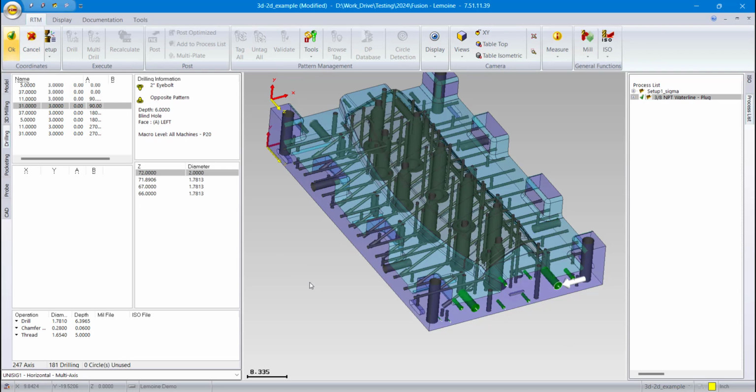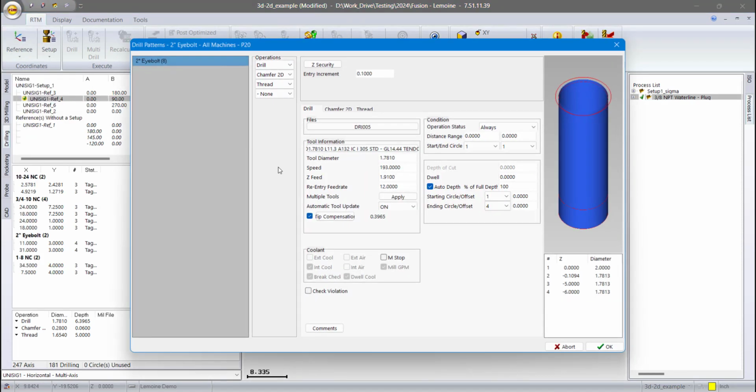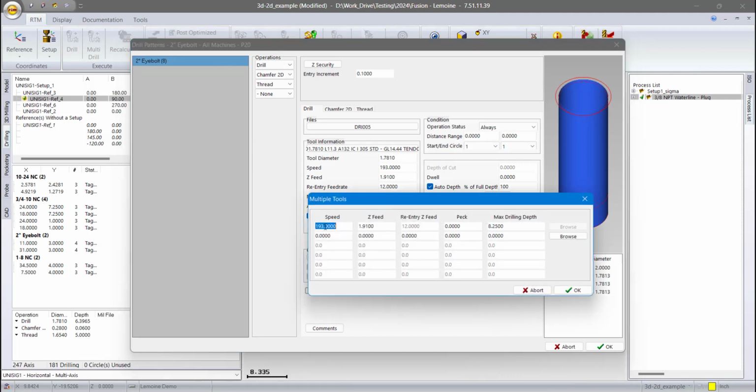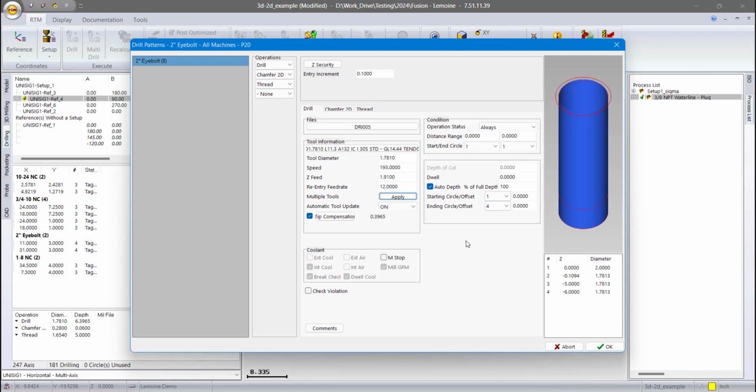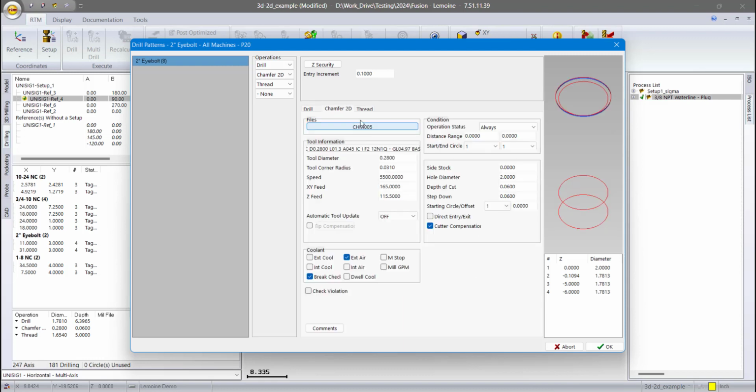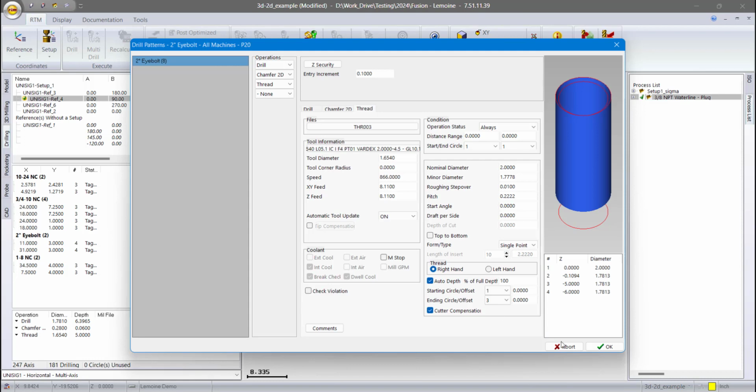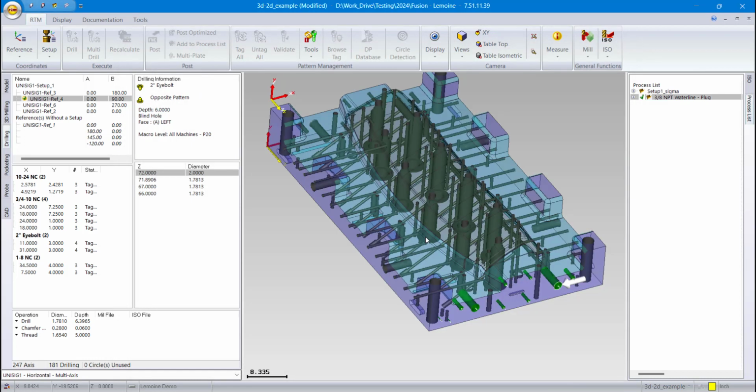And again, it'll bring up the milling forms that has all of the different tool paths. In these tool paths, what you'll see is that we have the order of operations. Here we can have up to 20 operations per direction, so 20 from the front, 20 more from the back. Any of the operations allow up to 6 different lengths of tools. So in combination, we could have hundreds of different programs work its way through here. We have all the necessary things that we need for this type of hole. So we click on OK. It'll make me a new process list again on the right-hand side when it's complete.